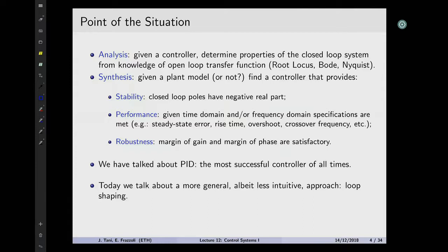So things like the overshoot, the transient time, the settling time, always defined for second order systems. And we're like, okay, but second order systems are a small little bit of things, but we saw that we can always, not always, but most of the times, we can approximate the behavior of a higher order system by choosing the dominant poles, and that basically tells us that we can look at the first or second order system simplification. So once we have defined these performances in the time domain, we said, okay, and this was actually something we will repeat today because I did it very quickly in the last 10 minutes of a couple of lessons ago, and it deserves a little bit more attention.